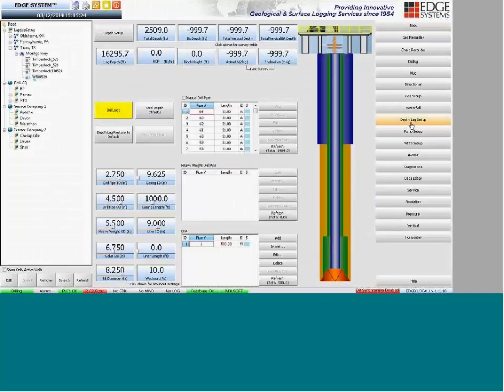In order to determine what the lag time is to get the rock and gas data to the surface, we have to calculate two things. The first one is how big's the hole, and you basically enter all the information about the drill string and the casing in this area here. You can import the pipe tally as it's known from the rig data, or you can manually fat finger it in if you're patient. And there's a heavyweight pipe here, and at the bottom is the drill collars. And these are all depicted over here in this little mimic diagram.